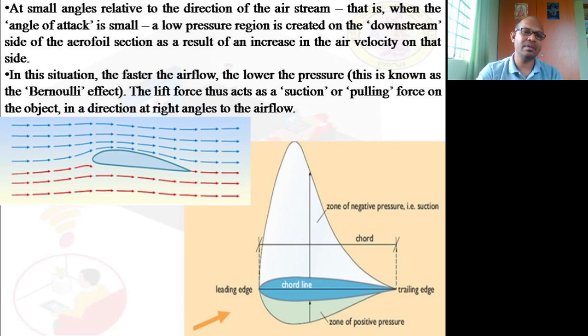So this is a wonderful concept of the aerodynamic system experienced by the blades. That is the reason why you don't see any rectangular plates or cubical plates. You always see an upstream with a wider shape and a downstream with minor trailing edges. It is only to make minimum pressure regions. The lower the pressure regions, the less noise it makes.